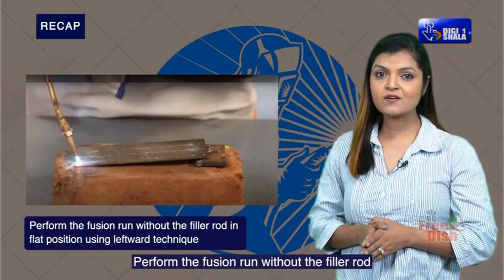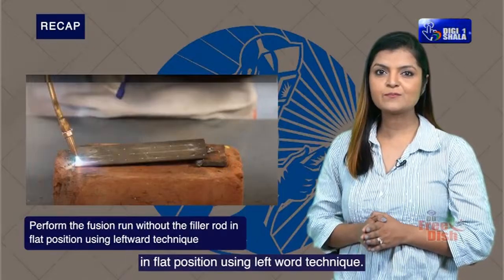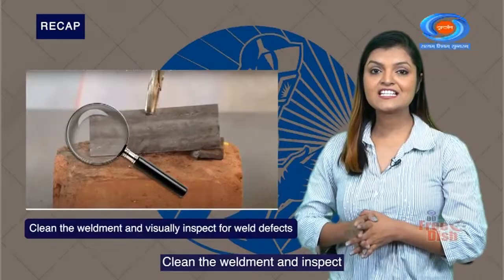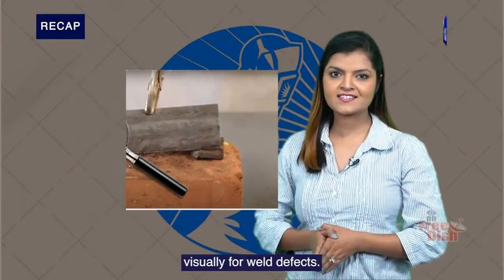Perform the fusion run without the filler rod in flat position using leftward technique. Clean the weldment and inspect visually for weld defects.